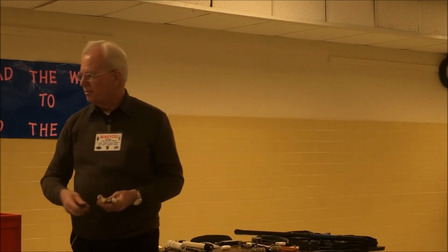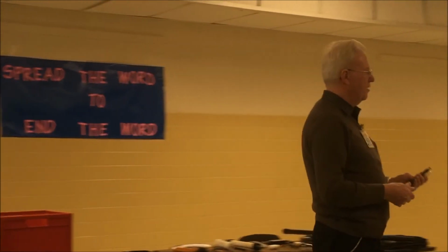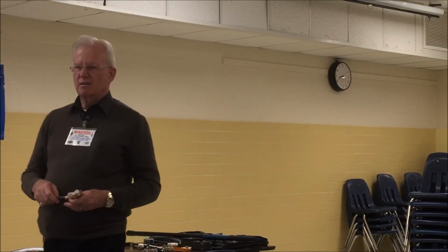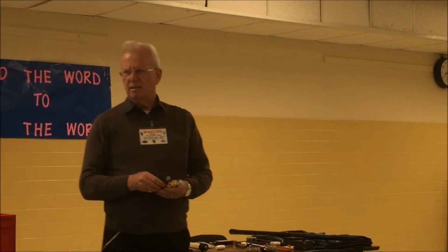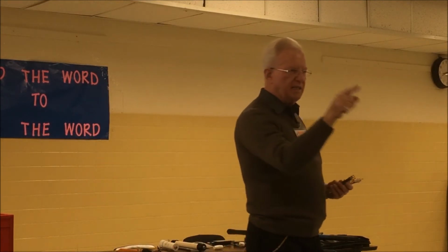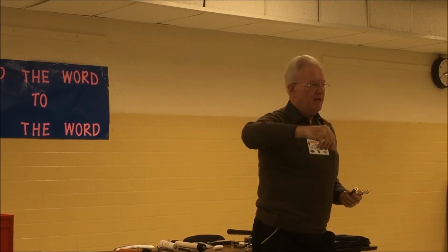These are pretty much the top 3, and guess what's taken over now, guys? Oh my God, you buy a walkie-talkie, what's on your walkie-talkie? The SMA connector. That's on your radio nowadays. And the worst part of it is that the radio has a male connector on it. The antenna has a female, which means you're going to twist the antenna on, and every time you twist the antenna on and off, you're wearing away part of the male pin.